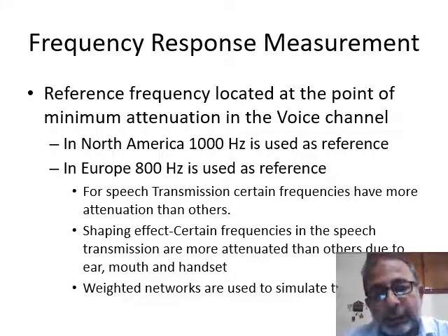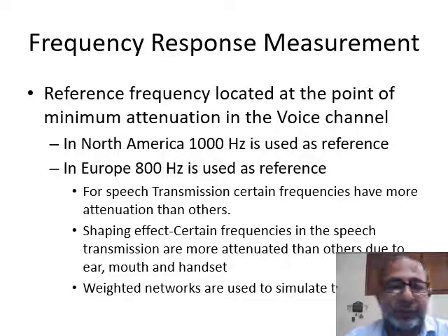Now, how do we measure the frequency response of a voice channel? We have already seen that there are two different ways of doing that, and there are two different standards for that. The North American standard recommends 1000 hertz to be used as the test signal, while the European standard recommends 800 hertz as the reference standard.